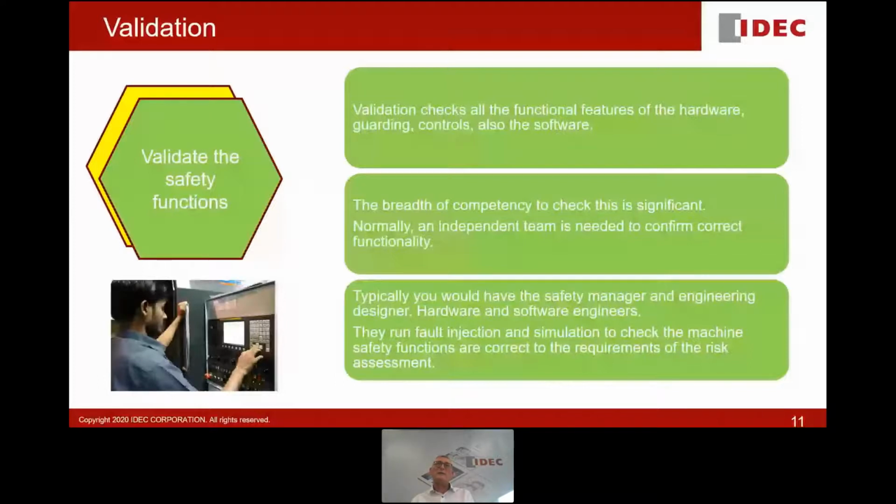Validation of the safety functions. This is probably the most critical part and involves the highest level of competency. We have to check the function of the devices, the hardware, the guarding, the control, and also the software, often neglected. The breadth of competency to check this is really quite significant. And normally you would use an independent team of people to validate the machine.